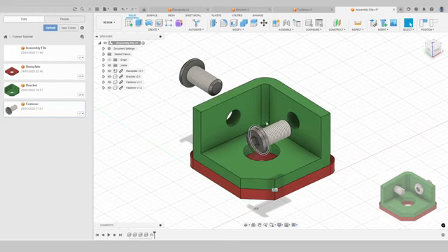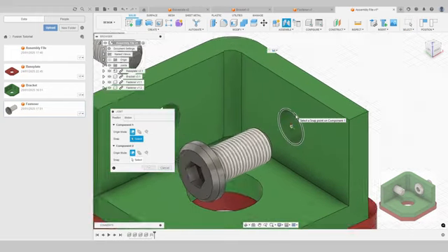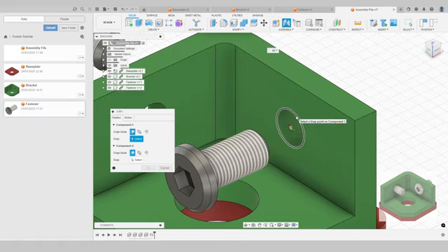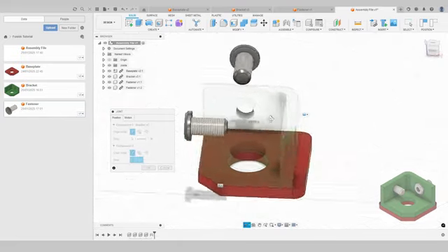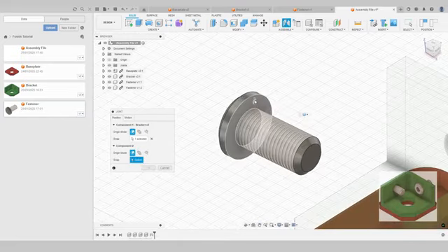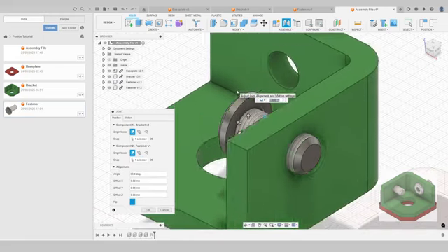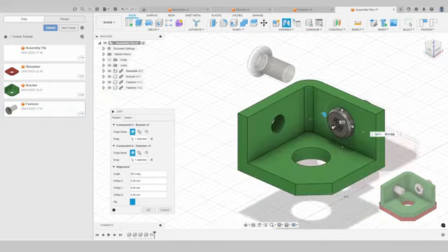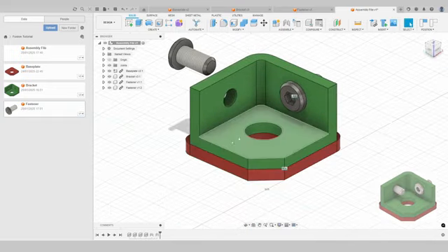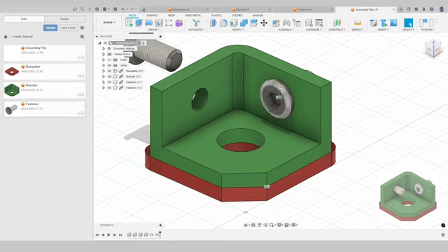Now let's do these two fasteners. So still, these are both roaming around free. Let's go to Assemble and Joint. And in this case, I want to make a joint between the center point of this circle, as we see is highlighted there. I'll just select that circle, rotate around, and come over to this circle here, and we can see its center point being identified there. So we select that circle. That is the mate that we want to have. That's looking good. Let's press OK. And again, that's a rigid mate. So again, I cannot move that fastener, cannot move the bracket, cannot move the base plate.